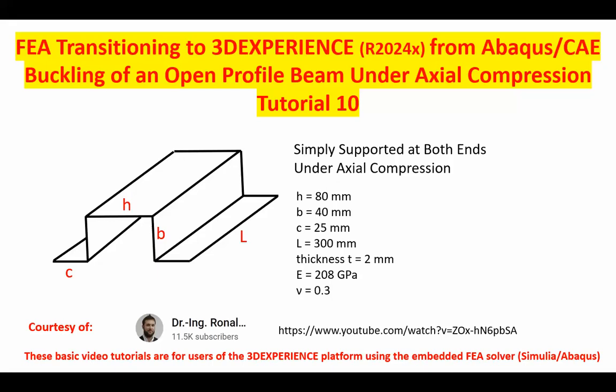So we have an open profile beam as shown here, and it is simply supported at both ends. The dimensions are given here, and the thickness of the sheet metal is 2 millimeters. We're going to do a linear buckling analysis. Once we find the buckling load factor, we're going to run the same thing under a linear static analysis and compare the results with a source that we have. And eventually we're going to do that as a nonlinear problem.